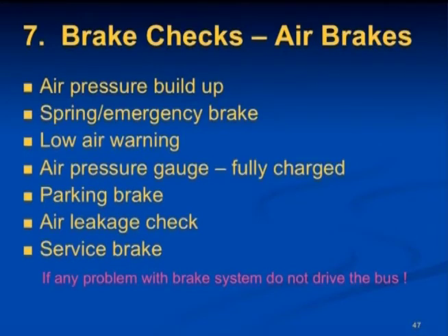With the service brake checks, make sure you don't wait until you're out on the highway to check those brakes. Test them at a low speed, bringing the bus to a complete stop. Before leaving the transportation facility, drive the bus about 5 miles an hour. Apply the service brake firmly. The bus should stop in a straight line without skidding, swerving, or pulling to one side. The brakes should not grab or lock or make excessive noise. Report any excessive pedal pressure or abnormal or unusual braking behavior. If the condition prevents safe braking, do not operate the bus until the condition has been repaired.